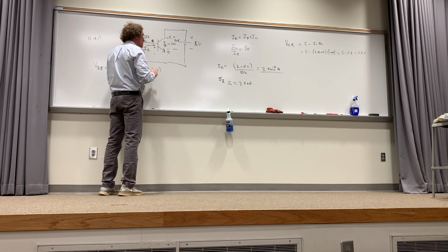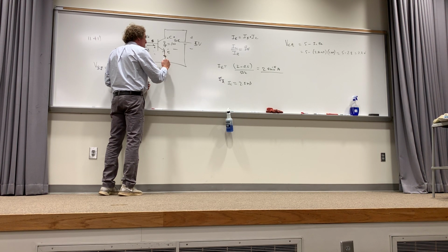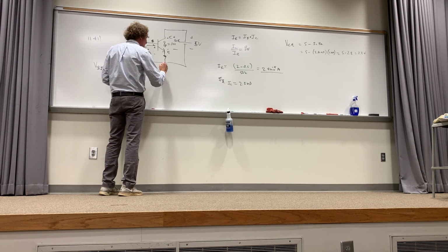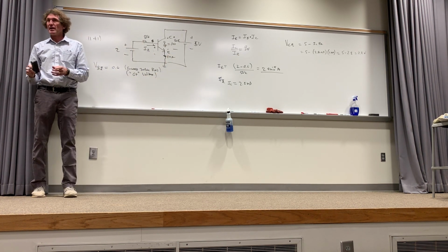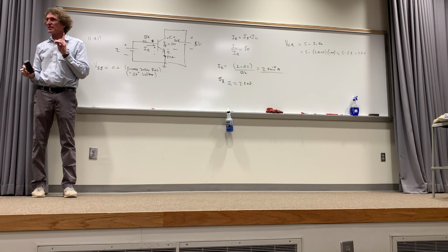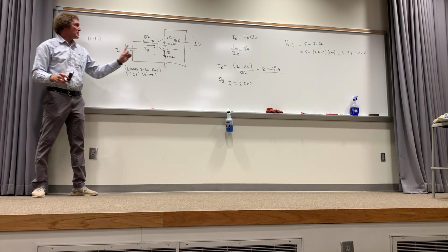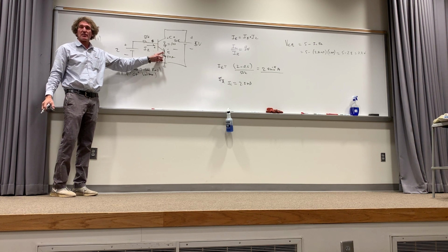I'm going to put a resistor between the emitter and ground. You can call that ground. And make this 50 ohms, all right? I'm only making it 50 ohms. Now please watch this. This is different, but you have the tools to do it. Now there still has to be 0.6 of a volt drop there. Follow me? But I want you to please watch this.